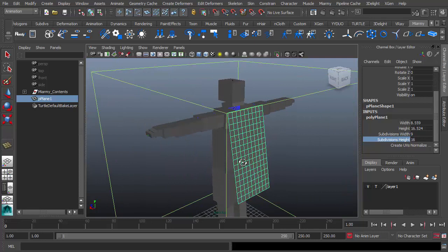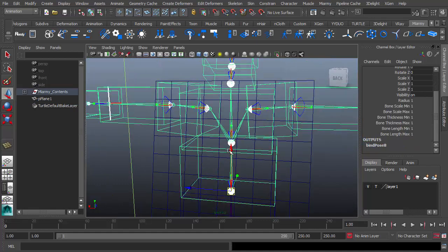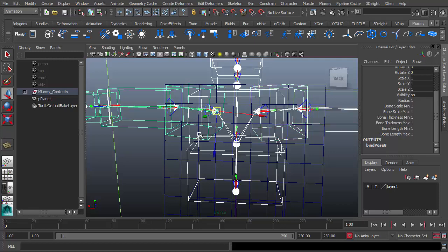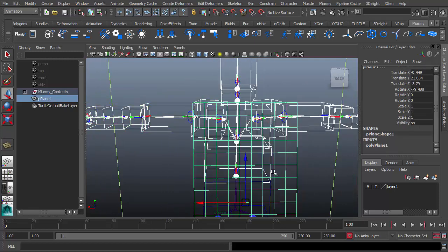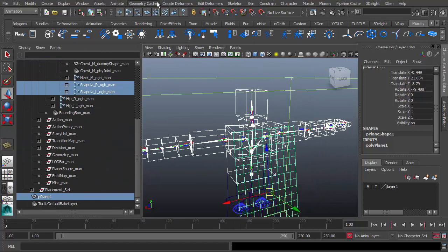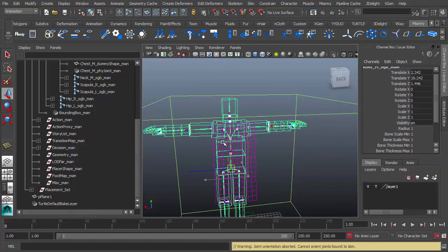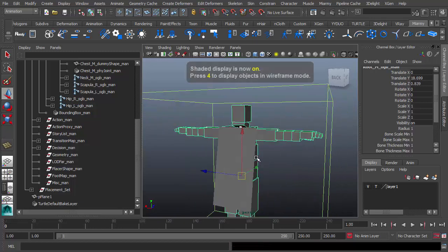And then the next thing we're going to do is bind skin the cloth, because our system can hold some of the points to this man with the bind skin. So what I'm going to do is select the free bones, this chest, the shoulder, the free bones, and select this cloth. You can see that we selected the free bones here and this cloth, and click animation skin, bind skin, smooth bind. At this time you can see that our origin agent can control this cloth just like this.